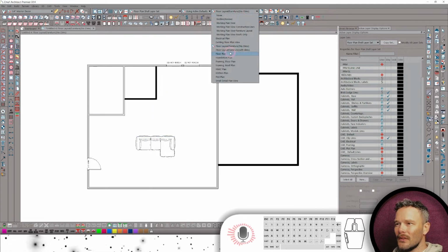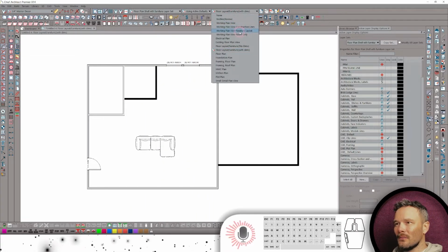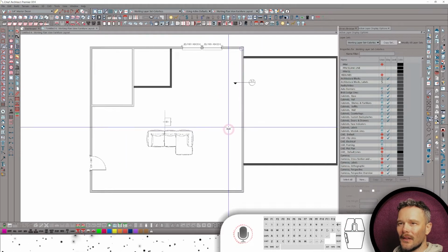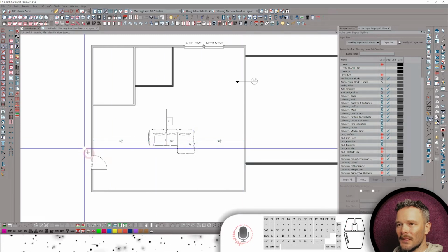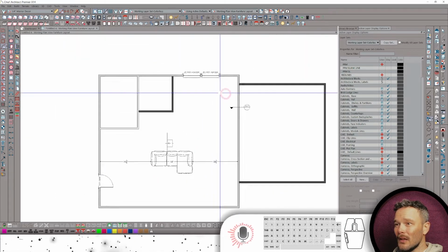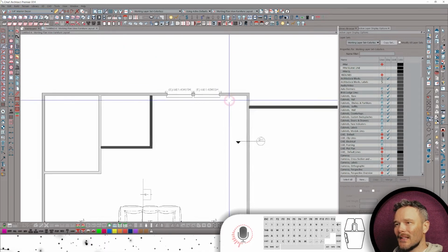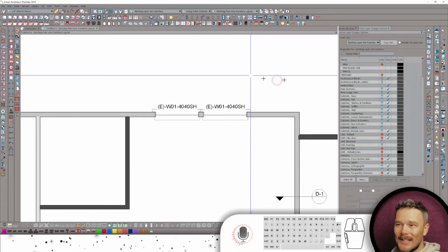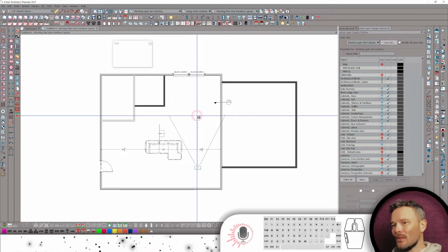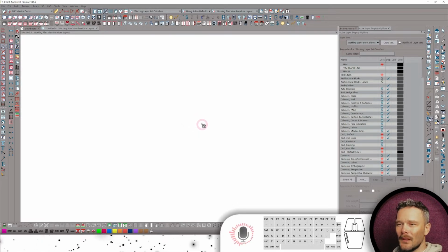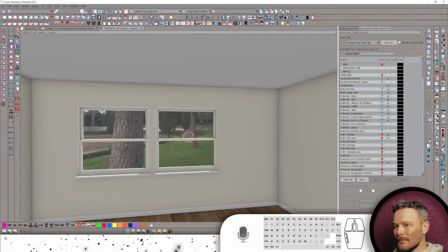If I want to switch to the floor layout, furniture with dims, that's going to drive straight from my working plan view furniture layout. So if we use our interior dimension tool and draw out some dimensions for this, there we go. Something else to note about the quarter inch interior decor dimension default is that it does measure to casing, but we need to pull a camera view to take a look at my windows and doors, because by default you'll see that my windows and doors do not in fact have interior casing, and there's a specific reason for that.